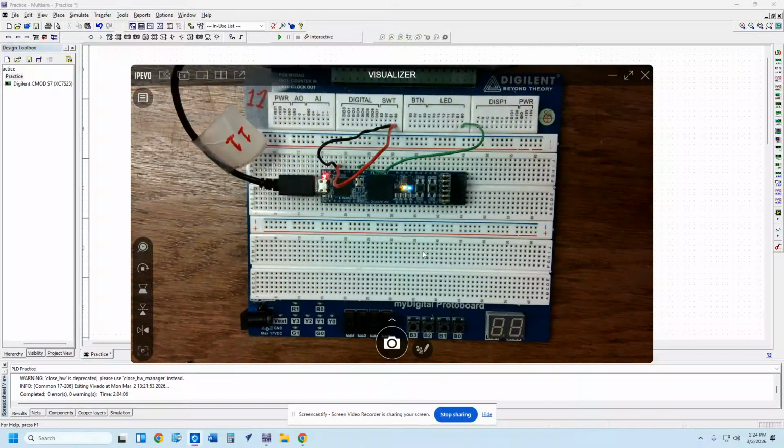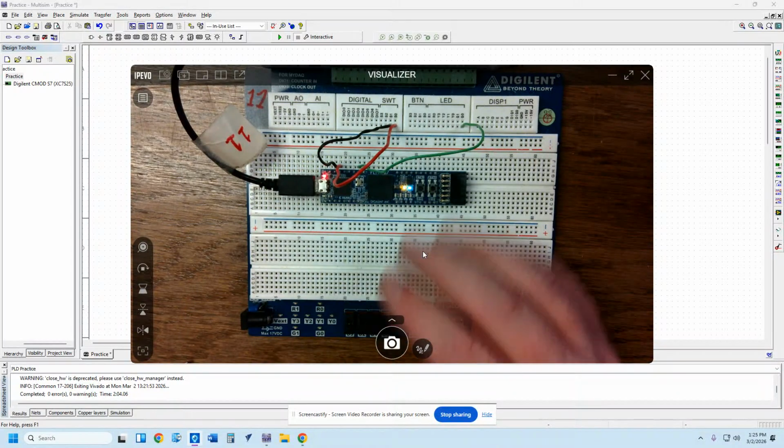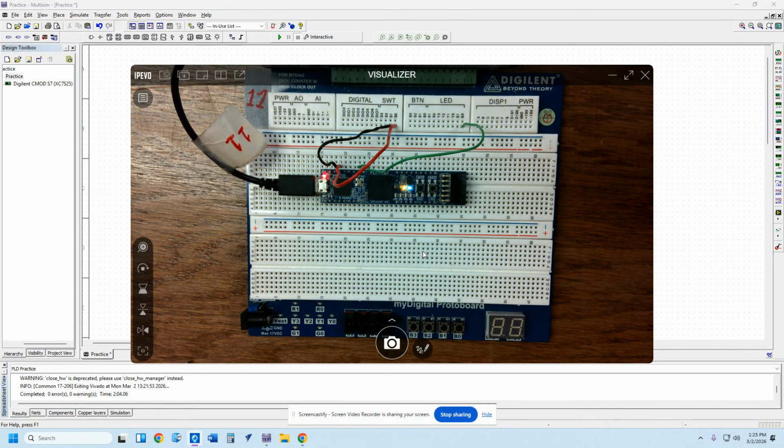Now people are like, hey Mr. V, can't we just copy the sim circuit over to PLD? Nope. Simulation circuit is basically la la land. Some of those things don't exist, okay? But the PLD circuit is real. Those are actual real gates and connections you're going to use. These programs do not see the same things. So no, you cannot convert PLD to SIM, and you can't convert SIM to PLD. You must redesign the circuit in PLD and program this properly. Won't work otherwise, right? It doesn't work.